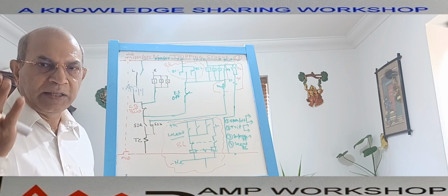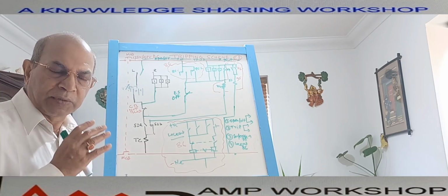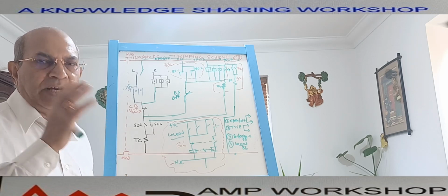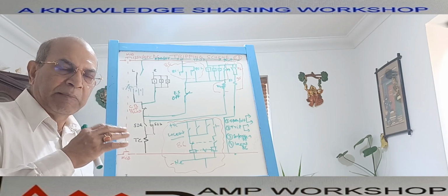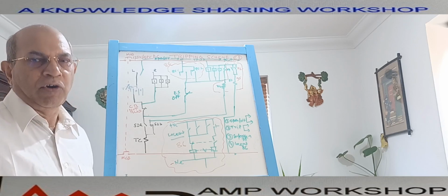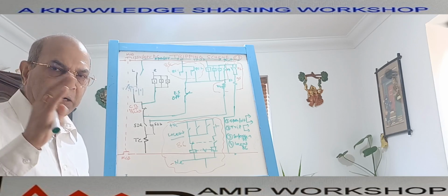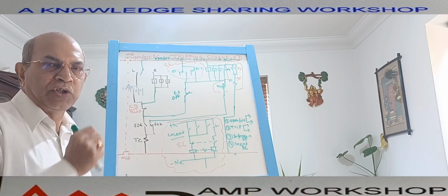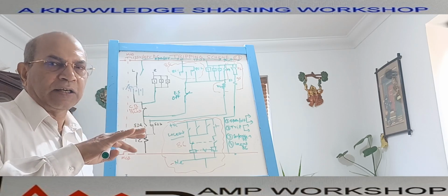Maybe there is a fire at the remote end, when this circuit is feeding power and there is a fire and gas signal or ESD signal. Maybe it is feeding power to another switchgear. That switchgear has developed a fault, for which it might have tripped or not tripped. In that case also we may give an inter-trip to the circuit breaker. That is also another type of fault.